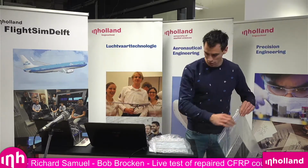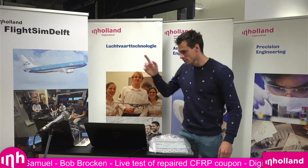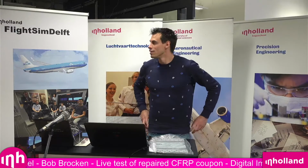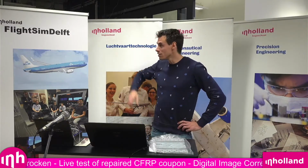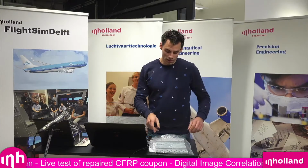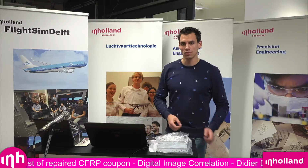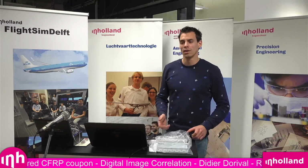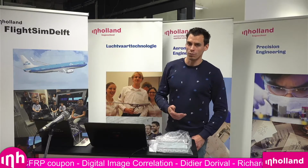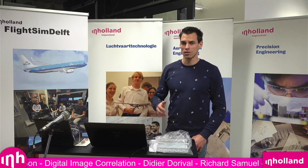There are a couple of questions. How accurate is this method compared to a normal strain gauge? Okay, so this method we've tested it on just general coupons where we applied both the extensometer and the digital system. And although there is some filtering happening on the extensometer, the actual resolution is nearly the same.